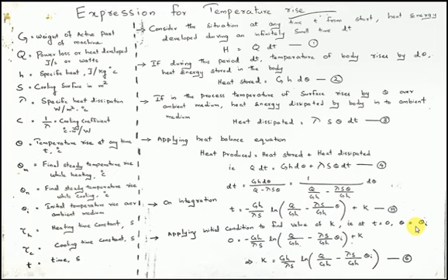It is actually both at time t is equal to 0, the machine is about to start only, so both the machine surface as well as ambient temperature will be having the same temperature. So definitely there will not be any temperature rise at time t is equal to 0. So at time t is equal to 0, theta's value also must be 0, because theta indicates the temperature difference between the machine surface and the ambient medium. At starting condition, this both must be same. That might be the doubt within you. I will explain that in detail.